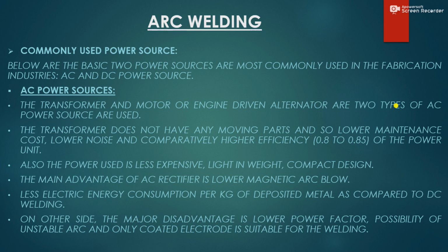On the other side, it has some limitations as well, which is that the power factor is very low. It is a very low power factor. There is a possibility of an unstable arc, and also only coated electrodes can be used for an AC power source.